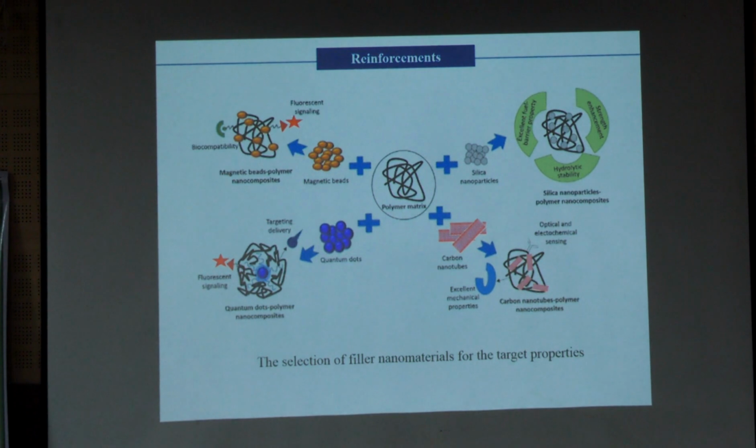So nowadays maybe the front part and back part of the cars, that is what we can call bumpers, are made of polymers. Okay, so this bumper is actually like a protector, so it should have high impact strength, but at the same time it should be lightweight, because the mileage of the vehicle, it may be two-wheeler or four-wheeler or anything, depends on the weight of the vehicle. So if you are able to reduce the weight of the vehicle, then you can get more mileage.